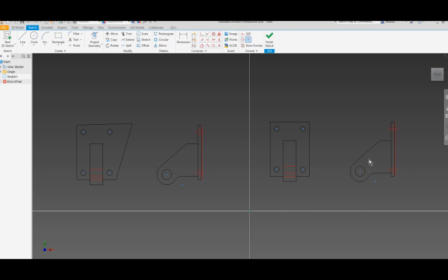If I also click on, say, this portion of the cylinder, I have the tangencies as shown. I click on this line, I click on this line, and it shows all of my constraints. In fact, if I highlight the whole thing, these are all my constraints. These are everything that I need to actually generate that particular part.